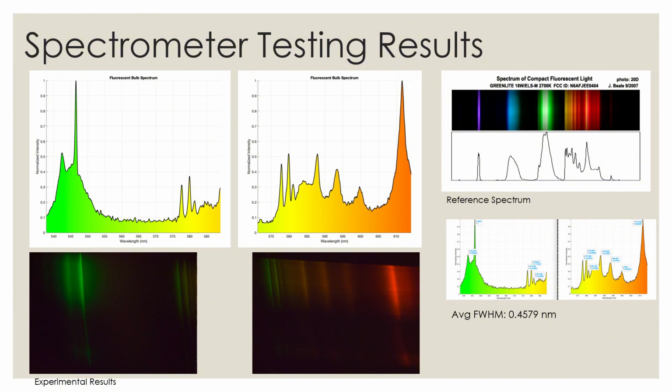To assess the resolution, I took the average full width at half maximum of the peaks across the two images. This resulted in a 0.46 nanometer full width at half max, which is within our spectrometer's resolution requirement. We know our spectral range requirement is met. This process establishes our calibration approach for integrating the spectrometer with the CCD in its final housing. The next steps include refining the spectrometer's alignment, integrating with the CCD, and coupling with the probe optics.